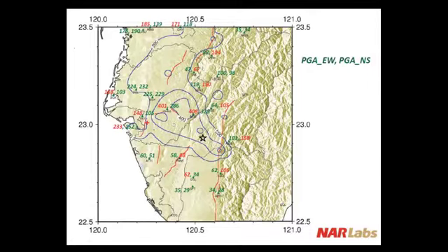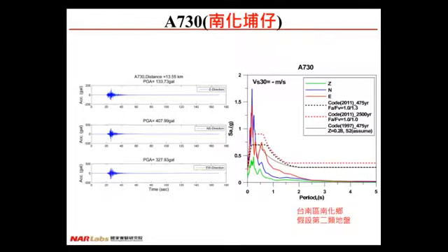This is the ground response recorded at station 730. It is a rock site, as you can tell from the peak spectral response at about 0.2 seconds. The duration is very, very short. It's about 8 seconds, which is about the right duration for a magnitude 6.3 earthquake.